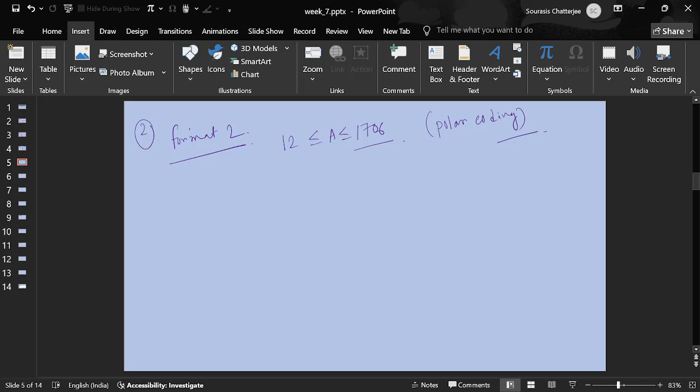Maybe I was thinking, DCI bits will be more, then it will be very hectic for the UE because it is doing blind decoding. And if some bits get corrupted, then the entire DCI will be corrupted. So our target will be to minimize the DCI bits, only sharing necessary information, so that decoding will be easier.